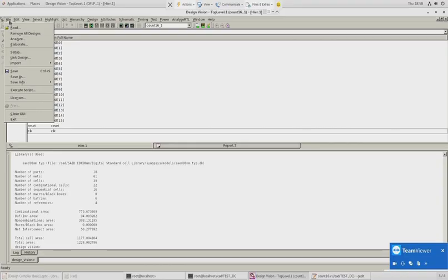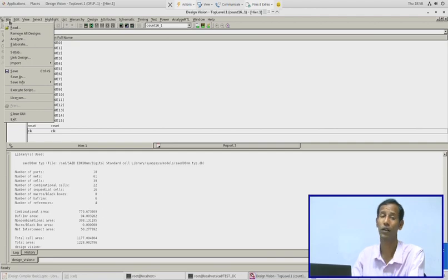For today, I think this is the beginning to start with. What I have left is this counter 16 module, and we will take this netlist file for the further parts of my design. That means for functional simulation, physical design, timing analysis, power analysis, everywhere we will use it, because this is a good example, as it consists of the sequential element as well as the combinatorial element.